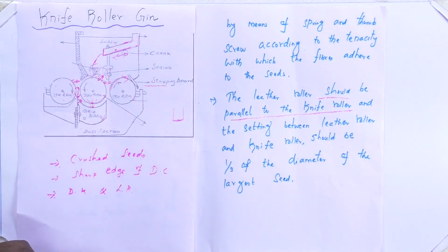So the summary of this class: the first topic is production of yarn by using various processes. The first process is ginning, second is blow room, then carding, comber, draw frame, simplex and spinning. These are the sequence of processes for producing carded yarn or combed yarn. There are two types of yarns available. If a fiber follows the carding process only, then the yarn is called carded yarn. If the fiber goes through the comber process, then it is called combed yarn.